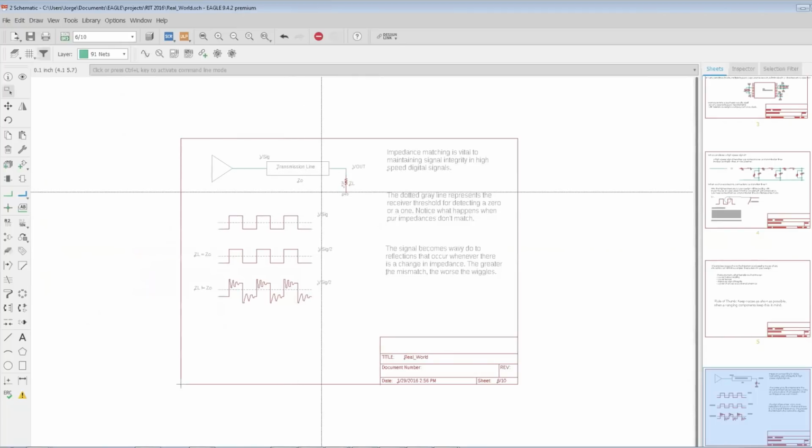So if you're in the high-speed regime, one of the big fundamental rules is to maintain constant impedance. And how do we do that? Basically, you make sure that your trace width is consistent the whole way through. Okay? If you can avoid vias, you totally should, because a via will affect the impedance. It will be a discontinuity in impedance. There will be a difference there. You will get some reflection.